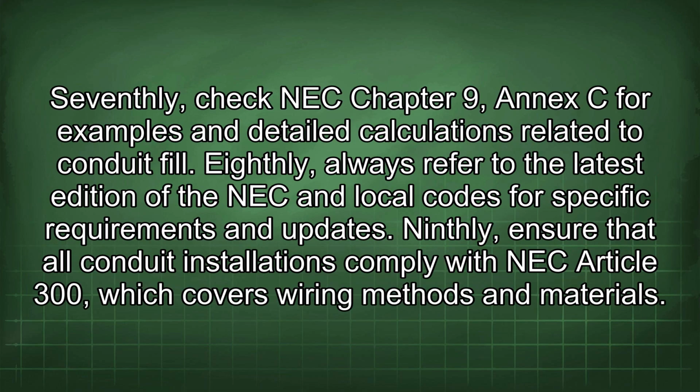Seventhly, check NEC Chapter 9, Annex C for examples and detailed calculations related to conduit fill. Eighthly, always refer to the latest edition of the NEC and local codes for specific requirements and updates. Ninthly, ensure that all conduit installations comply with NEC Article 300, which covers wiring methods and materials.